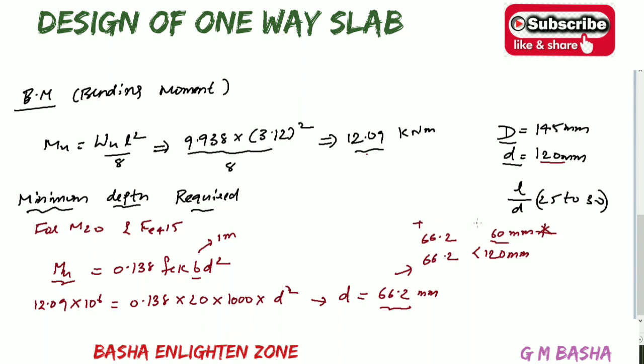You can restrict that value to here, but the minimum requirement is 66.2 and we provided 120, which means what we provided is higher than the minimum required. So we are safe in the depth. Therefore using 120 mm is safe, no problem.